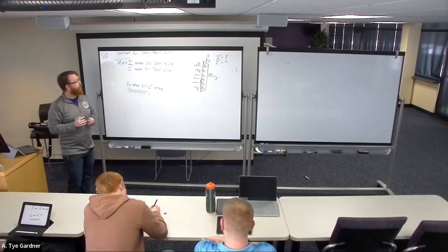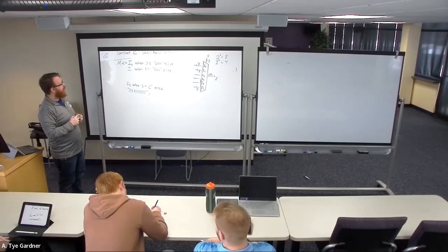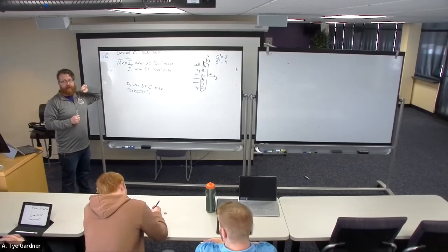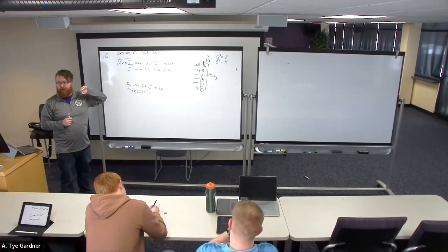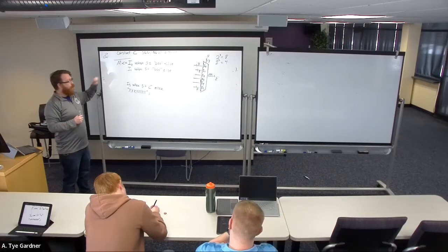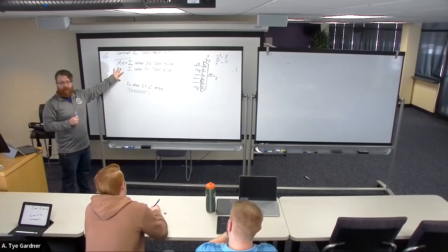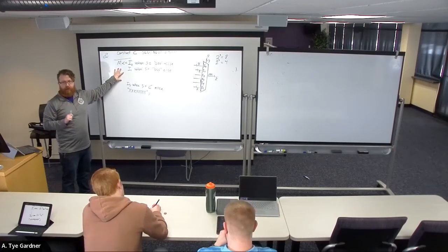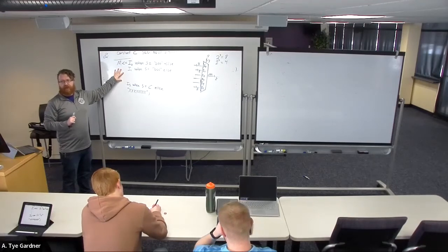So would this go in the architecture section or the process? This is inside the architecture, and this is combinational, so it doesn't need a process. We're going to run into some issues later on where there's one way to do this inside of combinational logic, which is everything we've done so far. Everything we've done is combinational, which is to say the output depends only on the combination of its inputs.